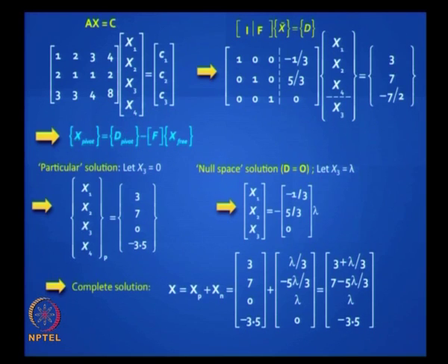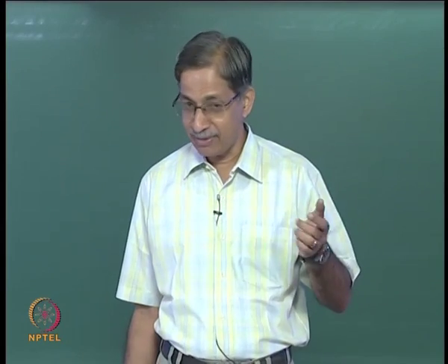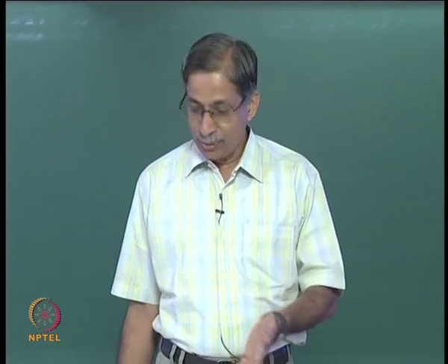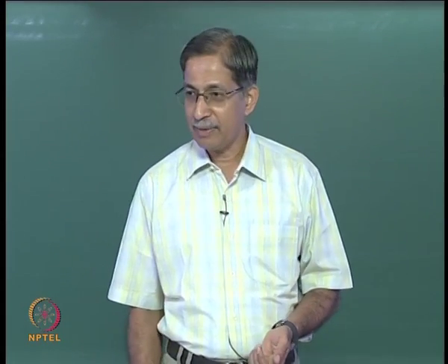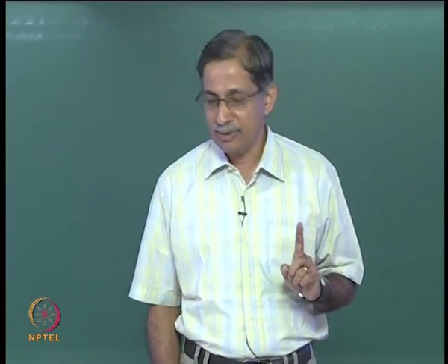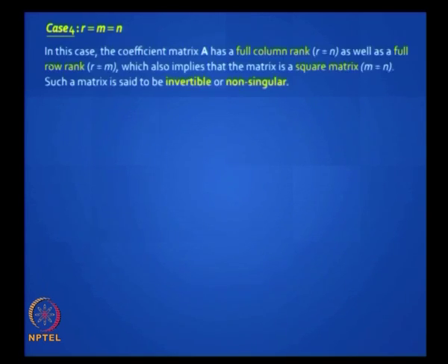We do not even do this. When did we do it? We wanted to find displacements in statically indeterminate structures after having analyzed them. Remember, there we chose lambda to be 0, so we did not waste time doing all this, because you need any statically admissible solution to apply the principle of virtual work. This case is straightforward, full rank if you are lucky, but if your structure is stable you are likely to get this situation, and if it is statically determinate, this is straightforward.